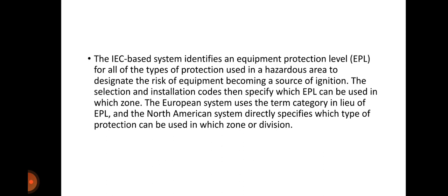Here, the IEC based system identifies an equipment protection level, EPL, for all the types of protection used in a hazardous area to designate the risk of equipment becoming a source of ignition. The selection and installation codes then specify which EPL can be used in which zone.